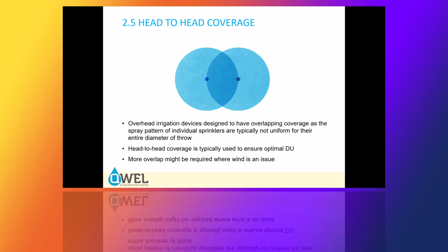Whenever possible, try to use drip irrigation in high wind areas so that we have less evaporation and overspray as a result. You'll have more direct application to the plants and their root zones by using drip as opposed to doing spray heads with excessive wind.